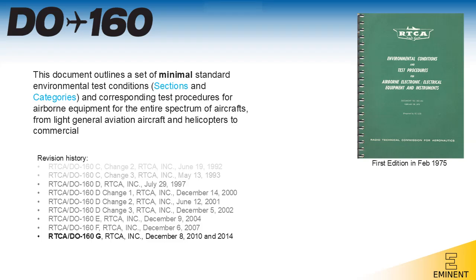DO-160 encompasses 26 sections, each targeting specific environmental conditions and hazards that equipment may face in aerospace environments. These sections cover an extensive range of tests to assess resilience under factors such as temperature and altitude, which ensures functionality across extreme temperature and altitude ranges; humidity and condensation, which verifies resistance to moisture buildup and humidity; vibration and shock, which evaluates the equipment's resilience to continuous vibrations and operational shocks.